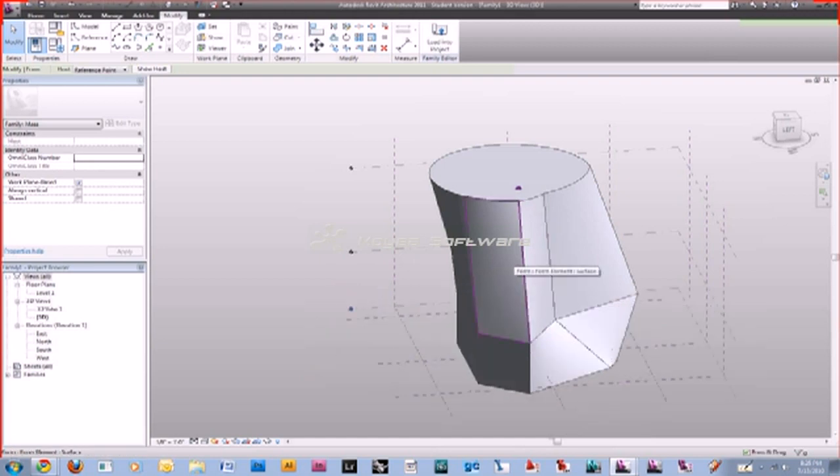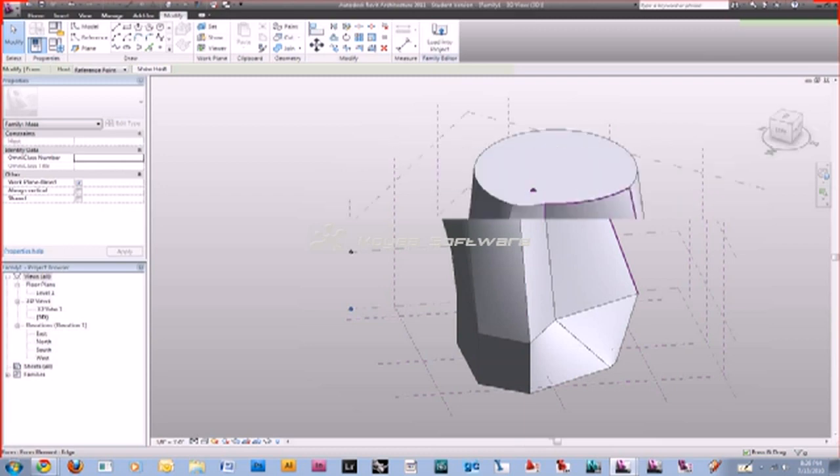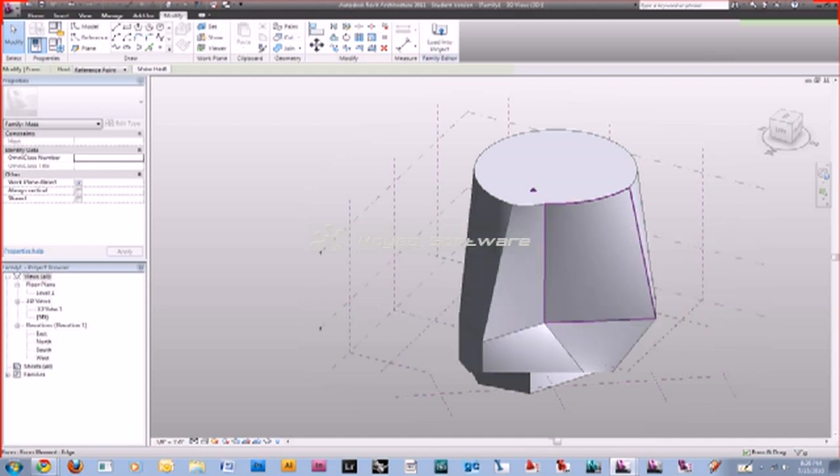So, all right, to move on to the last little thing we're talking about, which is probably a big thing, but we're going to break it up between now and the next meeting, is divide surface. And simply put, divide surface is how to add a texture to a wall that's really parametric and will flex with the wall at any point in time.